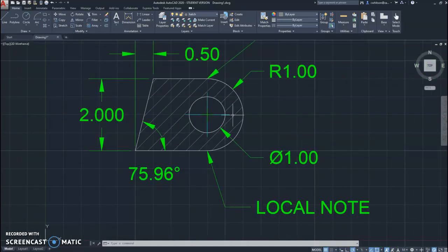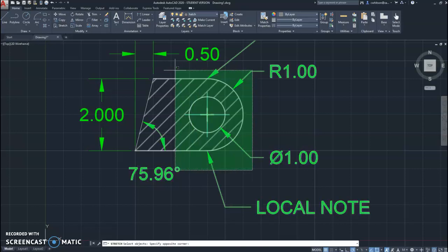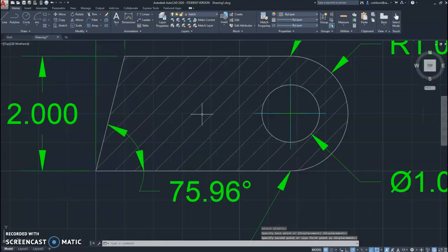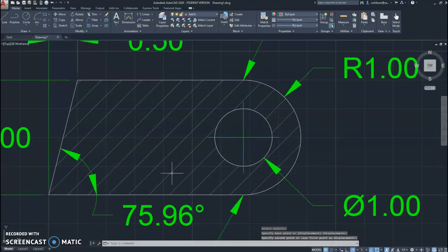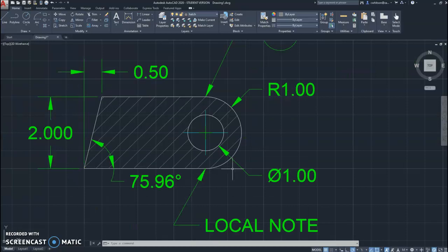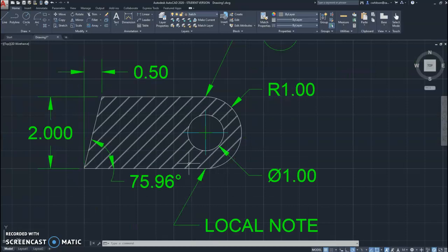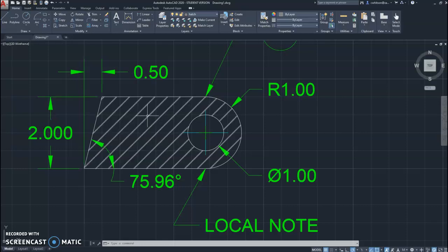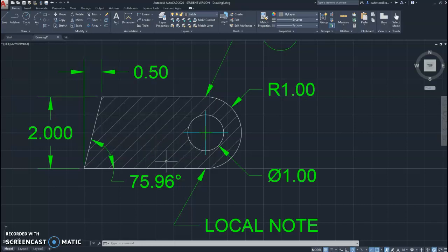Now, if anything should happen to that boundary, let's say I stretch out this drawing. Yeah, see, AutoCAD now will adjust the boundary, and the hatch just expands to match the new boundary of this shape. Back in the old days, AutoCAD wasn't quite that smart, and you'd have to delete the hatch and remake it. But you can see it's gotten a little bit better.